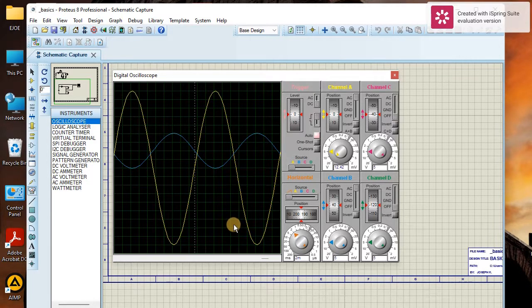But you have to convert to seconds, and by that we are dividing by 1,000. So 20 over 1,000 is the same as 2 over 100, which is the same as 1 over 50, and that is T. So your T is 1 over 50, and so the inverse should give you 50 Hz.